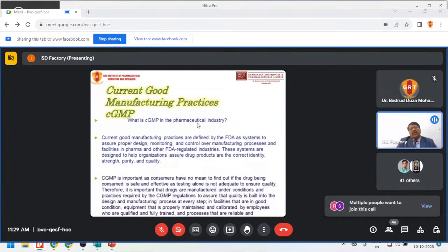So this is where we do each and every step of the facility, and all the materials will be tested before we go for the processing activity. In parallel, when we take the material into the stores, we follow first in, first out, the FIFO system. As per the raw materials, everything will be verified and checked, then we go for the FIFO system. Afterwards, it goes to the manufacturing area.